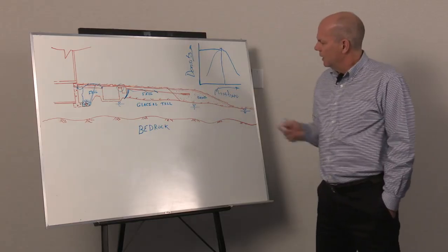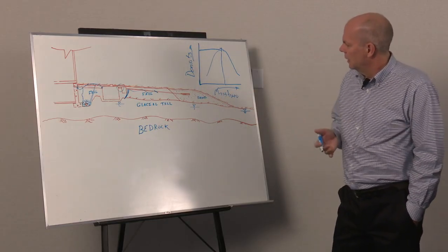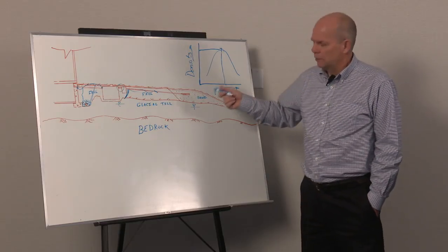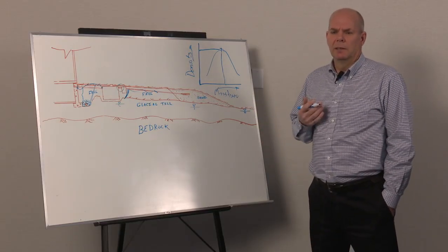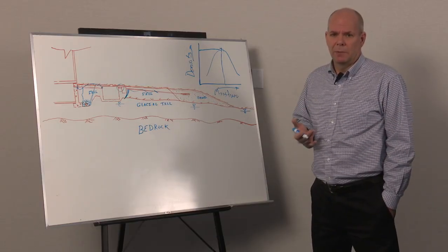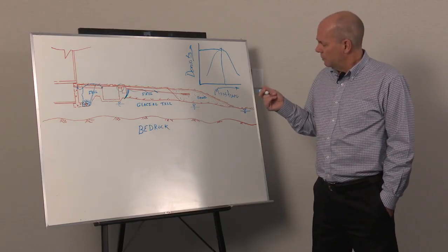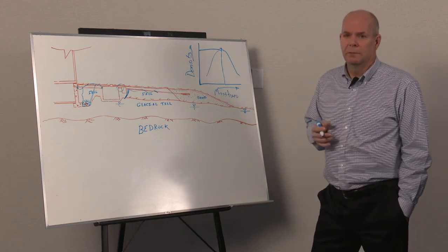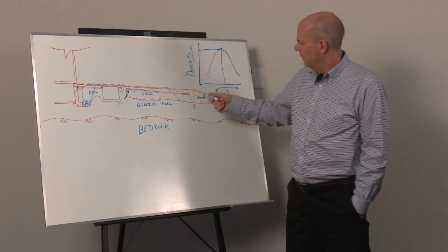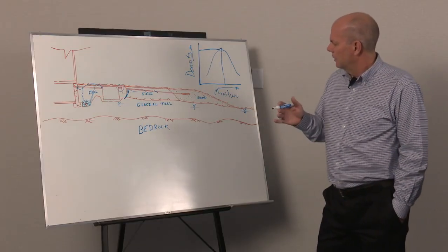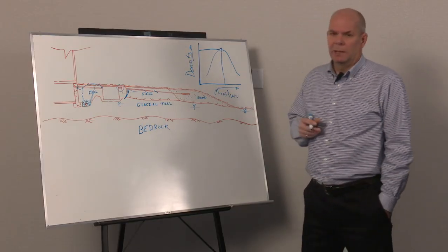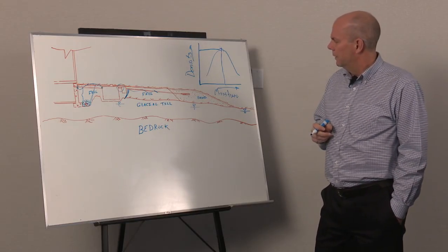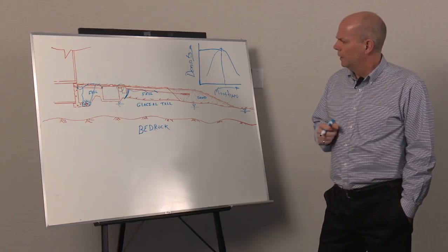So everything around this sand bed, and I think the regulations and the guidelines address it, should be done with minimal disturbance to that sand. Light equipment, light tracked equipment, stay off it as much as possible and place the material without driving on it at all if you can. But the settlement that happens there, you're going to live with. Don't be in there compacting it to change the permeability and the effectiveness of the bed.